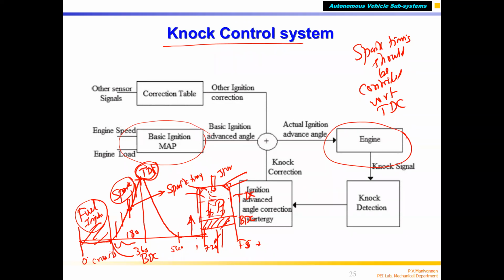Then the piston wants to go up, but the combusted hot gas, because I gave the spark very advanced here, very early, correct? I will put it in another color, blue maybe. You can see that I gave it here itself, just at the start of compression. The combusted gas will push the piston down, but the crankshaft is pushing up because in crankshaft rotation it has to go up to TDC. In between, you will not get power. So this is pushing down.